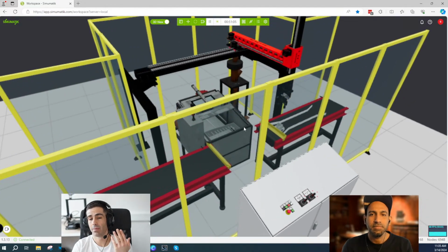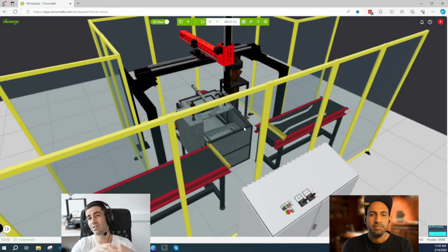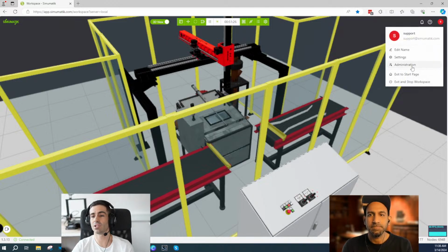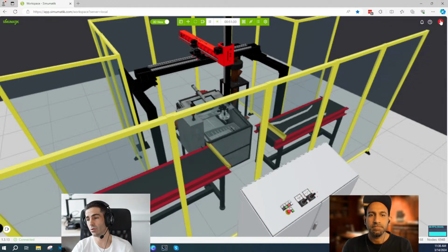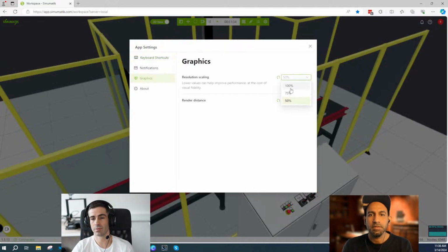It's mainly when you are running with integrated graphics cards, which require more RAM and even the CPU, because the GPU is not enough. You will give more room for the CPU to run the physics, the behaviors and the emulation itself. So it's quite recommended. And if you change that setting once, each time you start the app, it will keep it. So you don't need to be changing that setting all the time.